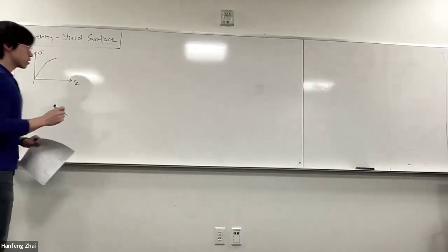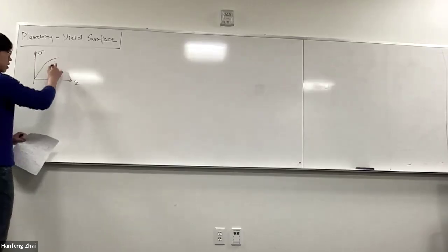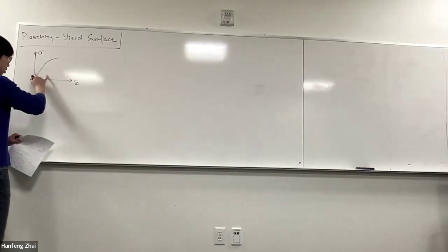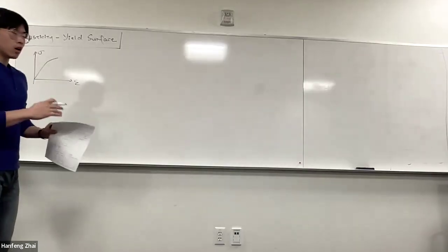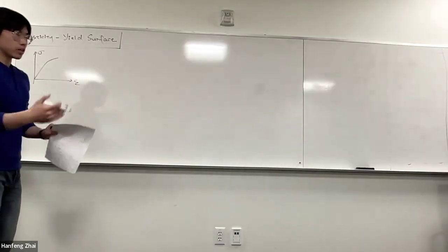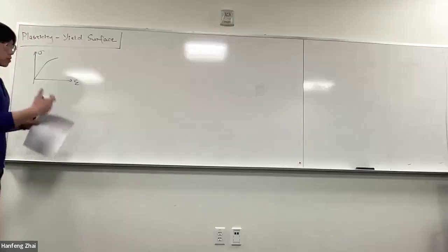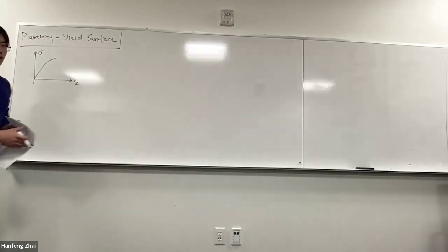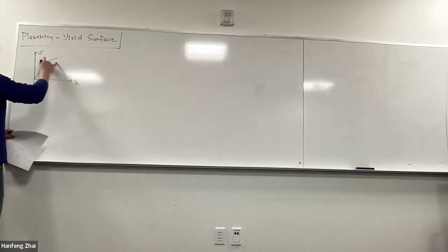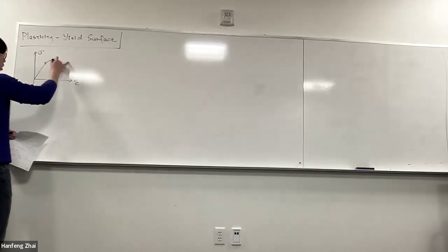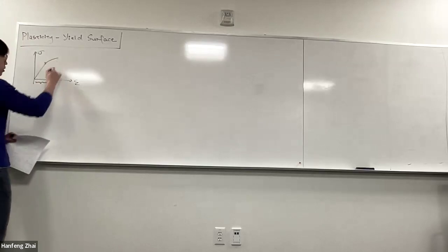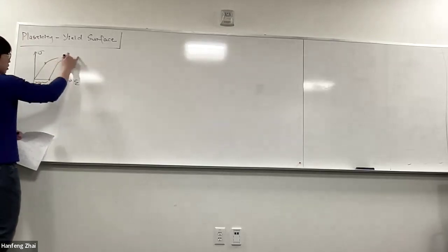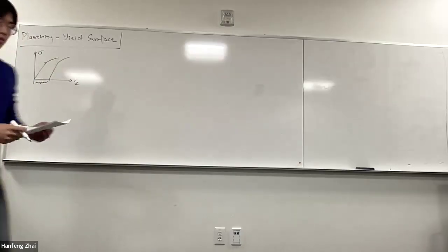Again, I have to emphasize, if you unload the material, and it goes back to the original origin, it means there is no plastic deformation. So not all nonlinear stress-strain curves are indicators of plastic deformation. But today, let's assume we're in the general context of plastic deformation. You reach a yield point, and if you unload the material, you generate a permanent plastic deformation, and then you reload it, which can be seen in the lecture note.